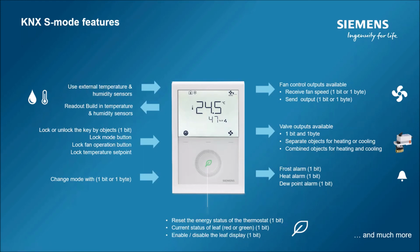In general, what we have started to do, and what we have been successful at so far, is to give the option of having 1 bit and 1 byte objects for most of our options. So you can change the mode, from comfort to eco or protection, with 1 bit or 1 byte. The fan speed is also available with 1 bit or 1 byte. You can also set the value straight away in 0 to 100%. But you can also read out with 1 bit or 1 byte and read out with 0 to 100%.